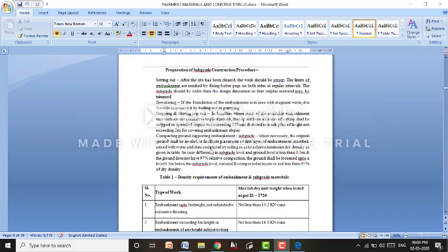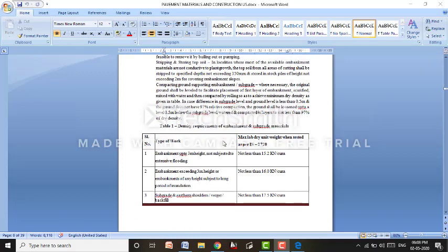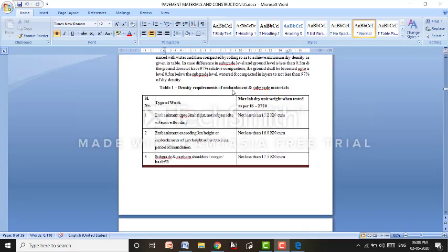So that's why if the thickness of soil is more than 100 mm, it needs to be compacted in different layers if you are using static rollers. If it is vibratory rollers, up to 250 mm in a single layer that soil can be compacted. If it is more than that, there will be a need for more layers for the compaction. And the compaction is to be done for 97 percent relative compaction. This 97 percent is calculated based on the lab density.